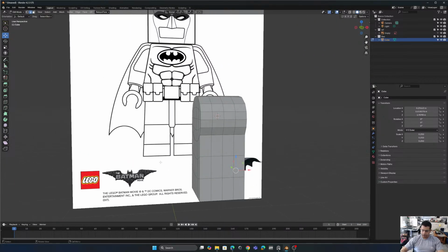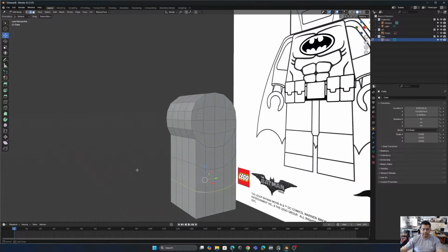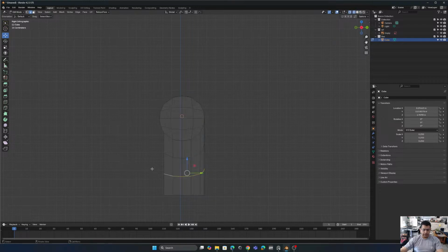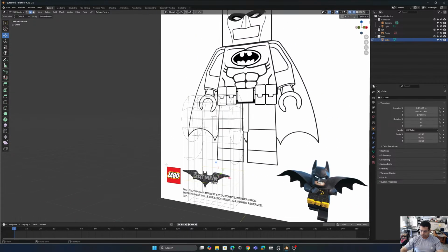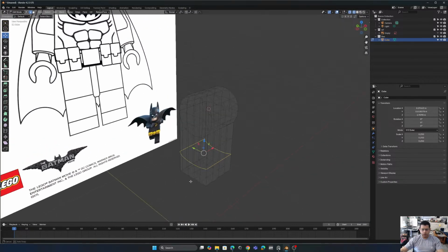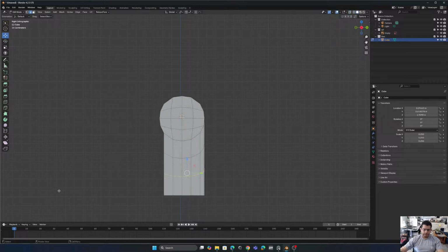So we're gonna go to 3, and we could select one edge and press Alt, and we're gonna select the whole loop, or we're gonna press Shift Z, or C, sorry, Z, and we could see everything through. So let's press 3, and we could select the whole loop, and as you can see, that also works that way. Well, we're gonna press again Shift Z.